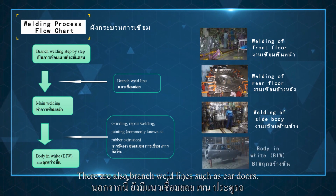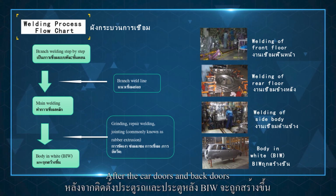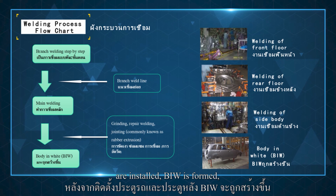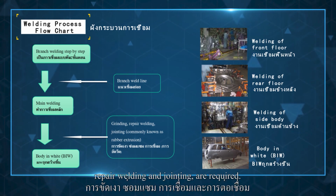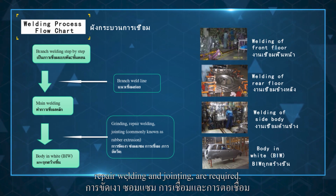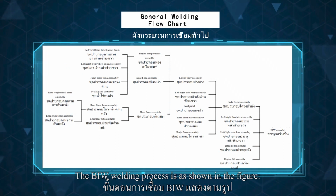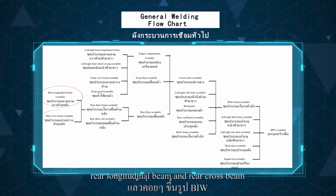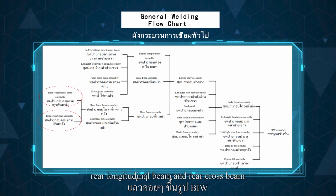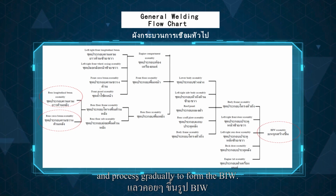And there are also branch weld lines such as car doors. After the car doors and back doors are installed, BIW is formed, and follow-up processes, that is, grinding, repair welding, and jointing, are required. The BIW welding process is as shown in the figure. Start from the welding of the rear longitudinal beam and rear cross beam and proceed gradually to form the BIW.